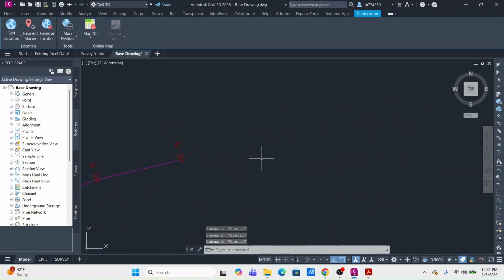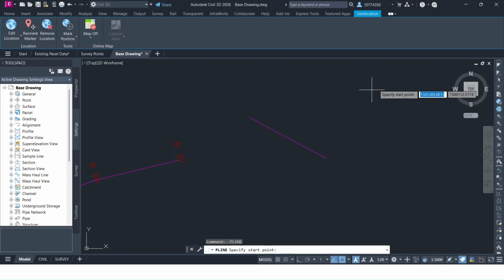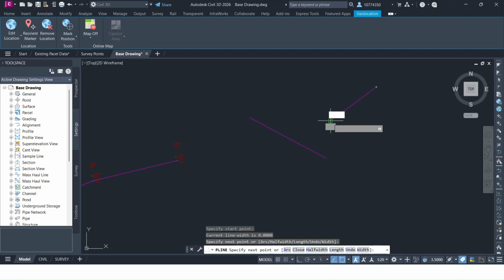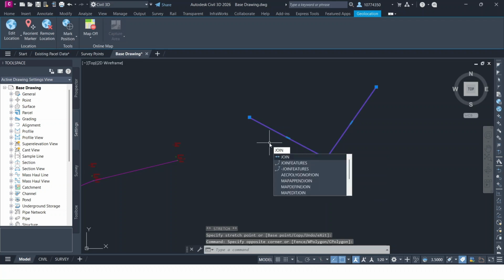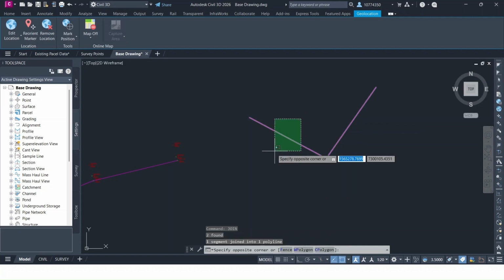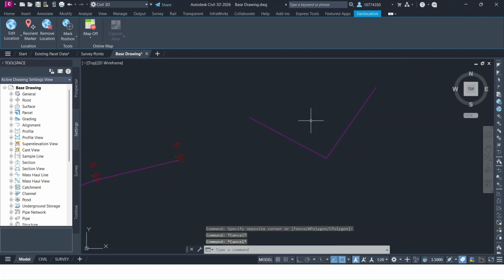You can join polylines as well, which is also a super useful feature of them. Let's say I had this one here and this one here. I can snap it to this endpoint, then select the other one, type join, and enter. Now they become a uniform line. One big old line here.